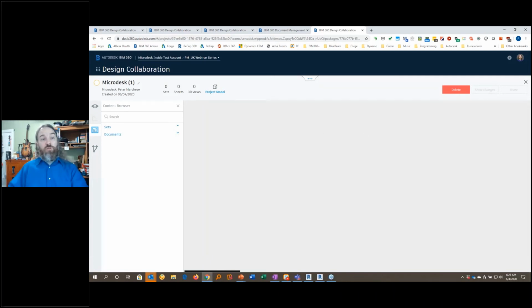I would go in here and choose what content I'm going to add. If I have Revit files, what Revit files am I sending? What views in that Revit file do I want visible in the browser? If there are additional documents, cut sheets, PDFs, specs, I can attach them here. At the moment, I do not have the ability to add AutoCAD files to the packages. Again, something on the roadmap. But this is where I would say, okay, this is the content that I want to send to the other company, and I'm going to put it all together so that they get this. So I'm just going to switch to another project that already has a lot of this set up.